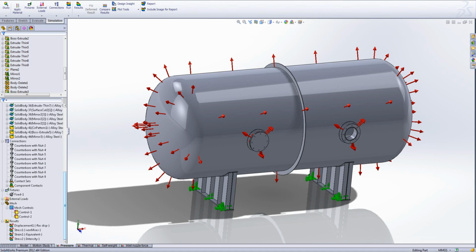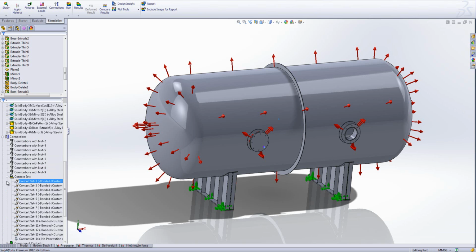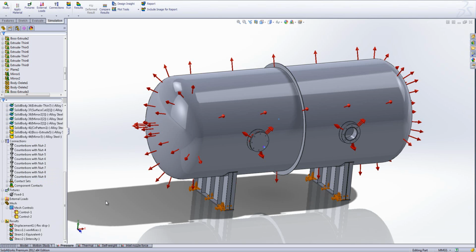It's worth noting that you do still need to make sure that they are pointing in the right direction. You'll see we have got three solid components at the bottom here, and these are our nozzle flanges and the nozzle cover just there. And we've used those because they've got geometry that lends itself more to the solid elements than the shell elements, and we'll come back to that in a moment. We've got some bolts that we've used here to fix the cover onto the nozzle, and we've also got a number of contacts set up. I won't go into that too much.